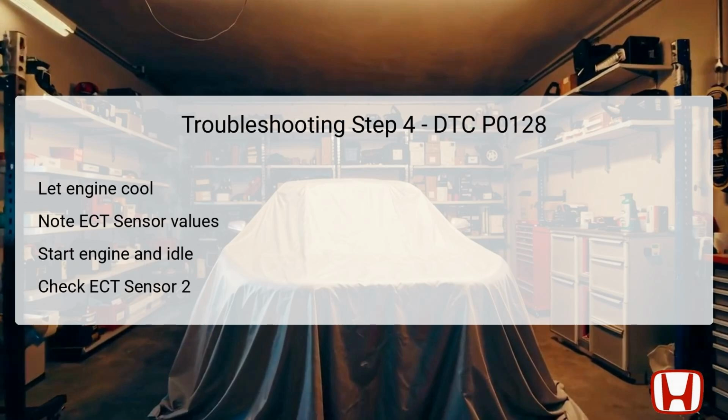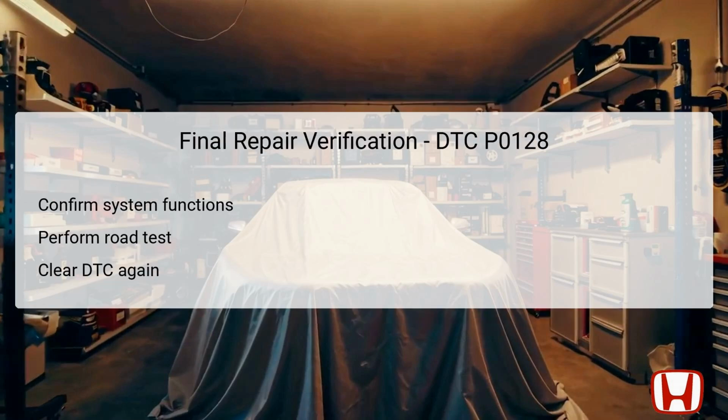within accepted norms. The final repair verification step is crucial in ensuring that the cooling system is functioning as intended after addressing the DTC P0128 issue. It's vital to confirm that all systems are operational, including the ECT sensors, radiator fan, and thermostat. Following repairs, a road test is recommended to accurately gauge real-world performance, validating that the cooling system maintains the correct temperature under different driving conditions.